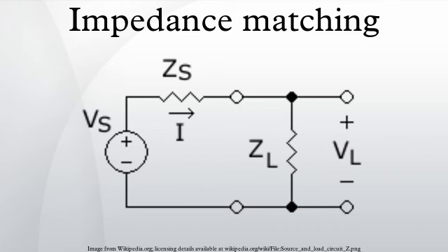If a reactance is in parallel with a source, the effective network matches from high to low impedance. The L section is inherently a narrow band matching network. The analysis is as follows. Consider a real source impedance and real load impedance.